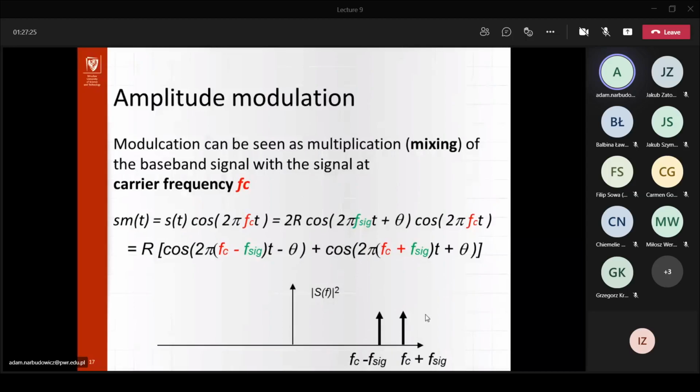If you go back a few slides earlier, what I was telling you, you have to bear in mind that even though we change the frequency to a much higher one, in the time domain this is still a real valued signal, because this is just an amplitude modulation. So again, we will have the counterpart of the complex conjugated signal at negative frequencies. As long as we deal with a real signal, this relation has to be there.